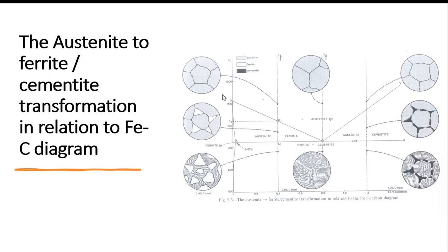just here you have austenite. Then the carbon amount is 0.4, here 0.8, here 0.4. Austenite, so after this line you can see the change, that is austenite plus ferrite here, and below 723 you can see ferrite is there, and again pearlite, right? So that is how it changes along the vertical line.